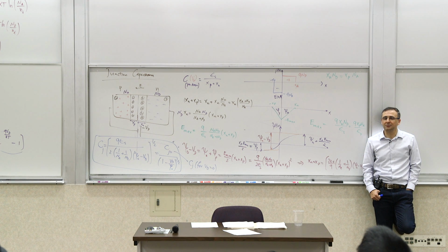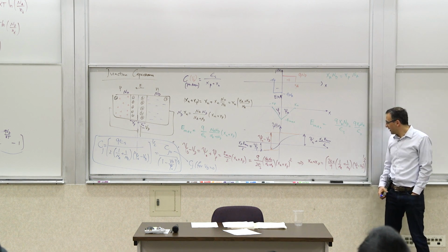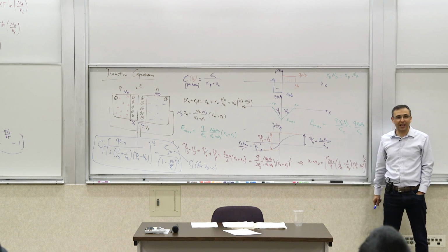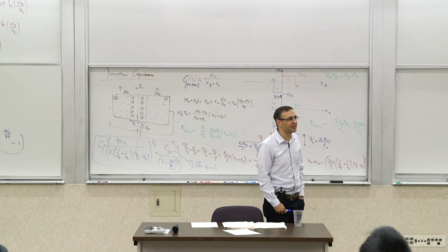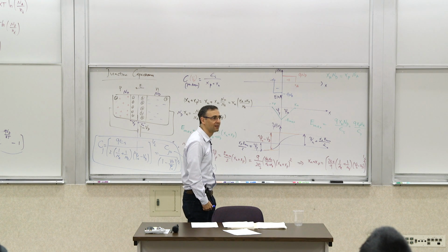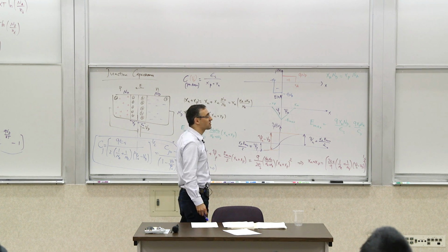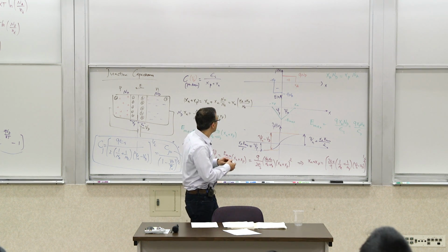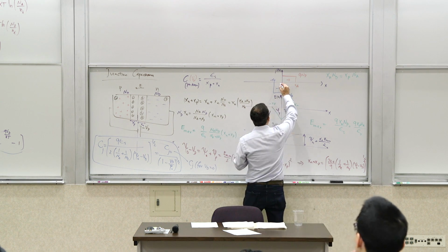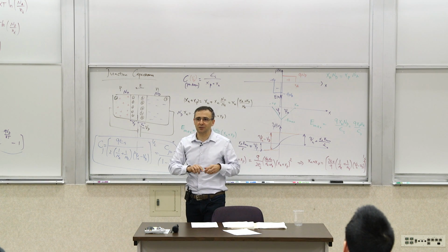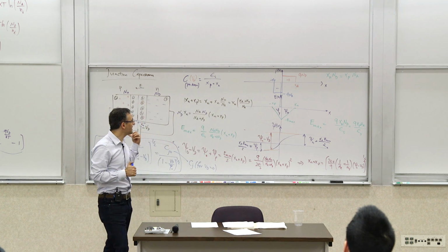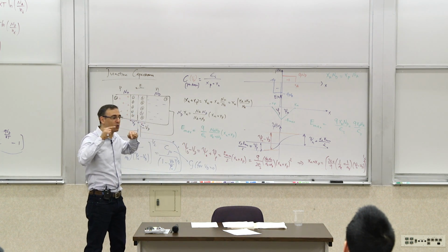If you wanted to get a narrower depletion width, increase the doping, right? Now, if I increase the doping of one side, what happens? If, let's say, I only increase Na and not Nd, what would happen? You will shrink just one side of it, right? So let's say if I had increased Na, this rectangle would become like that. But it still has to be equal to the other side, which basically means that, now this is an important statement,